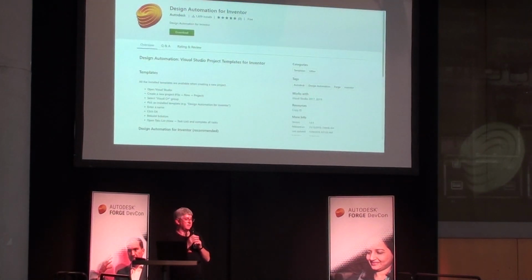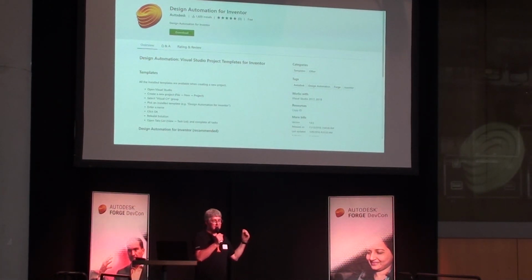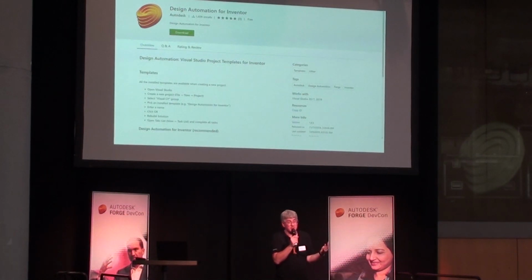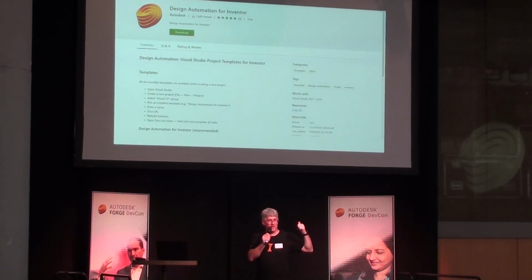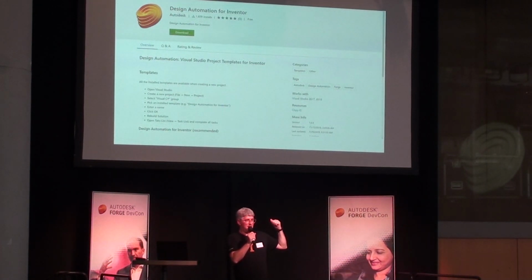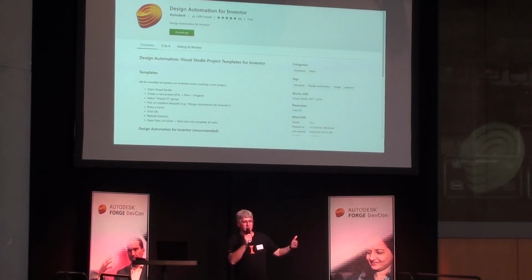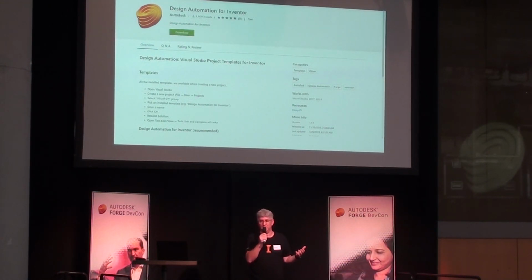All right, so a couple of practical places on where to get started. This is the core of where you're going to want to go to start your add-ins. This is what I use for those core references that I showed you, but if you want to start from scratch, go get the Visual Studio template that we have up online right now. I think we had over 1,600 downloads when I made this screenshot. I think once we get to general availability, this number is going to go way up. This creates that debug local, the interaction to upload your app bundle, as well as all of the bootstrapping code to create the plugin, create a GUI for you, register the column object, all the nasty stuff that you'd have to figure out, it just generates for you.